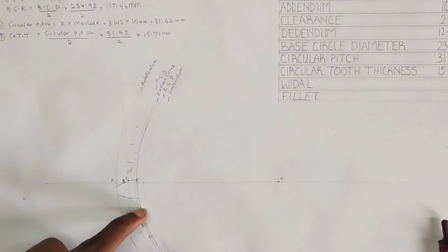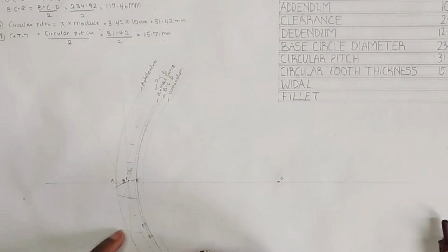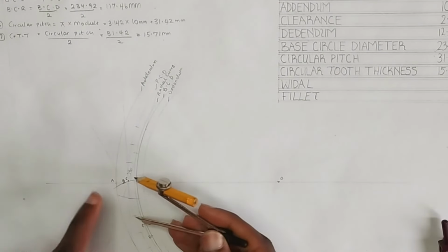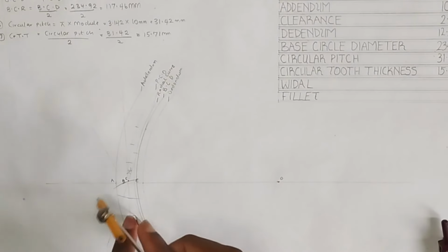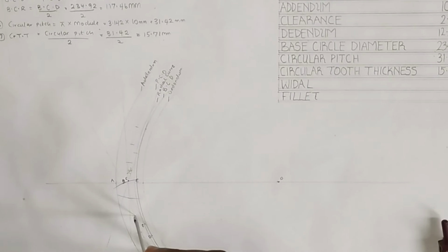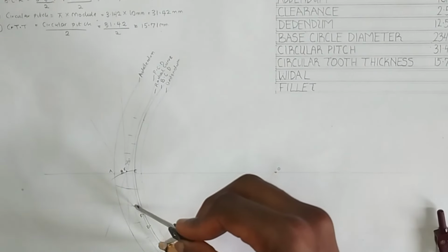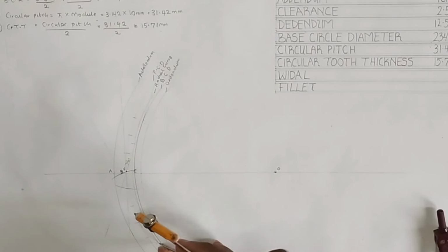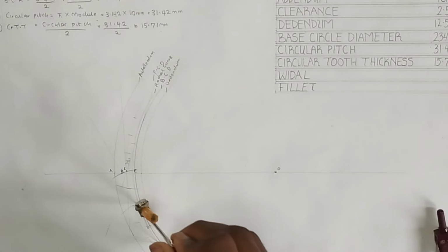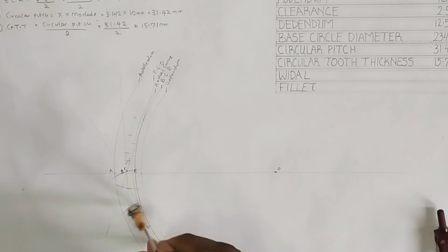So this particular place is going to come like this. In order to draw a curve that comes like this, your compass has to be around somewhere here, which is now going to make it curve like this. So using that same length of FB, I'm going to place my compass on this second point here, then strike an arc here. This is the place.